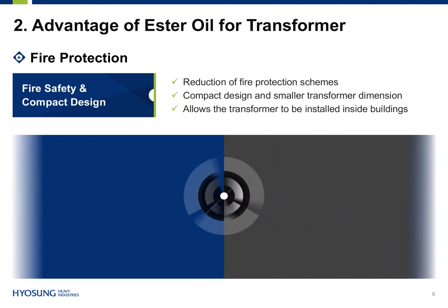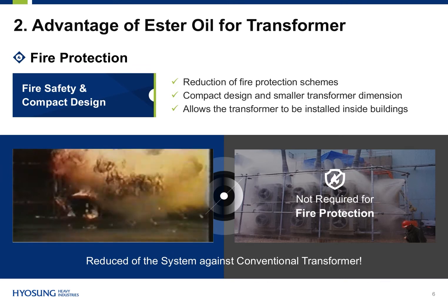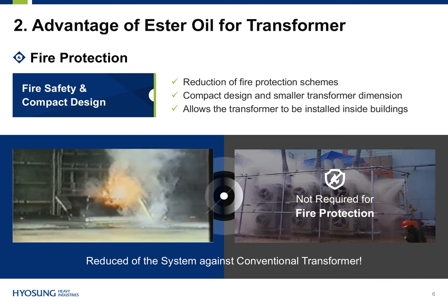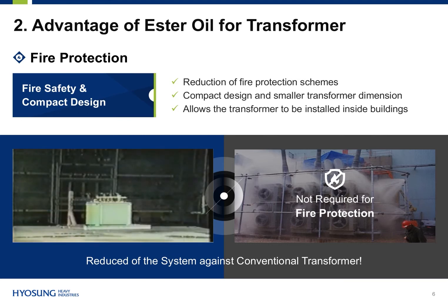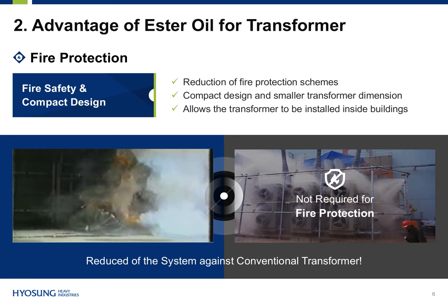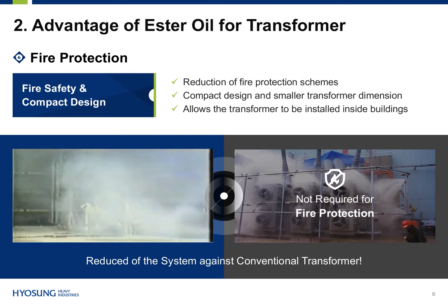We will now see a video of an explosion test for a synthetic Ester Oil. You can see that the fire is self-extinguished. Developments in Ester Oil transformers provide clean fire protection advantages. Since synthetic Ester Oil has a high fire point and self-extinguishing characteristics, it is possible to reduce fire protection schemes such as firewalls and costly fire protection systems. With Ester Oil insulation, it is possible to install a transformer inside a building, even a residential or commercial building.